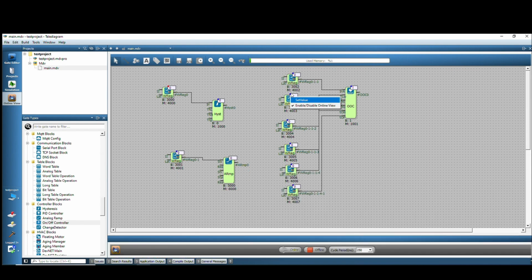We entered 20 for the lower threshold value and 30 for the upper threshold. We said if it's between 20 and 30. Now let's talk about the value we will send. For example, we sent the expression 21 and the on-off control output became 1 because it is within that range. When we sent a value of 31, which is not between the values, we saw that it switched to 0.